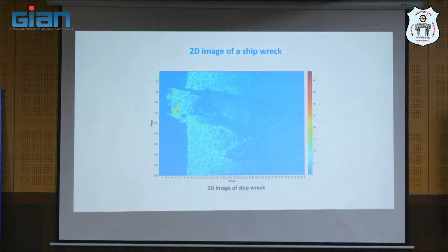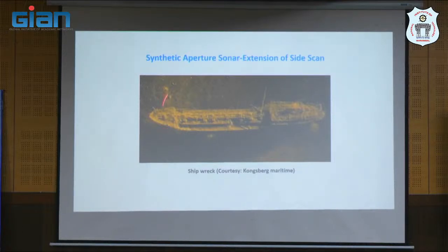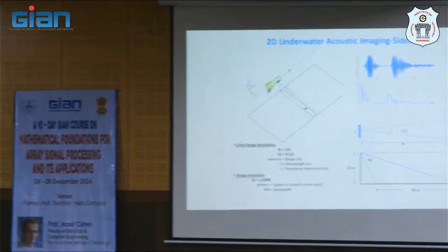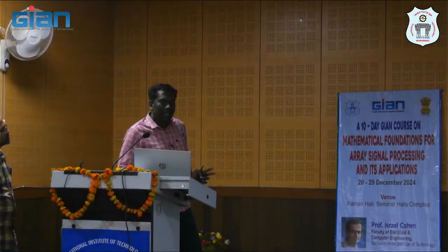There are methods to increase this, called synthetic aperture processing. What people have done is extend this array virtually. Physically only this array will be there, but by movement of this we can make a virtual array of higher length. As the array length increases, the resolution will be higher, so we will get high resolution imaging. But the challenge is how to ensure that the virtual array represents a larger physical array. Probably people have addressed this with AUVs, but still how to make it stable.